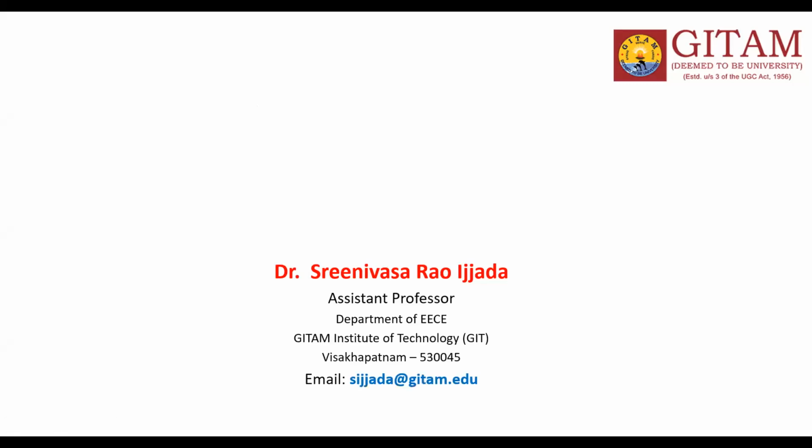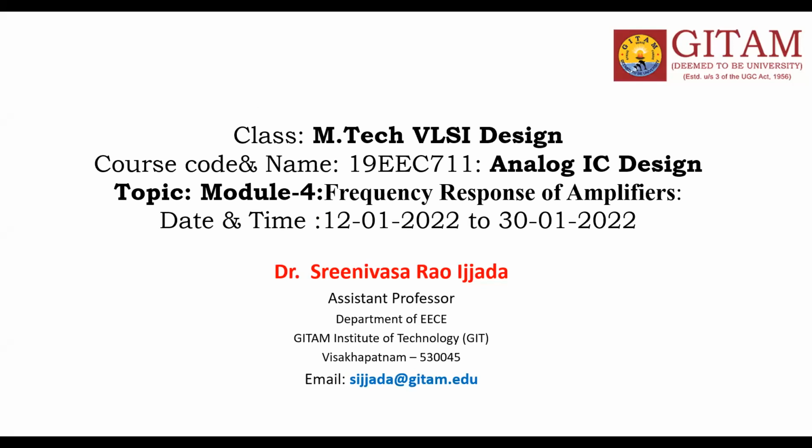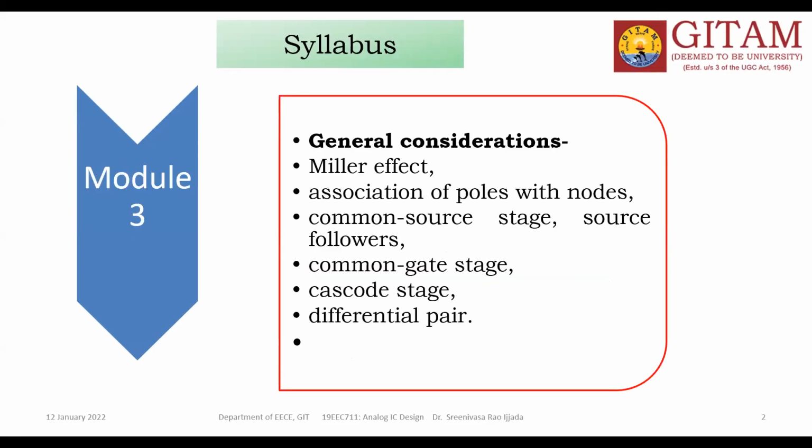So today I'm going to start frequency response of amplifiers. The contents of this module: Miller effect and poles and zero concept, common source stage, source follower, and common gate amplifiers frequency response, and later cascode stage and differential pair.